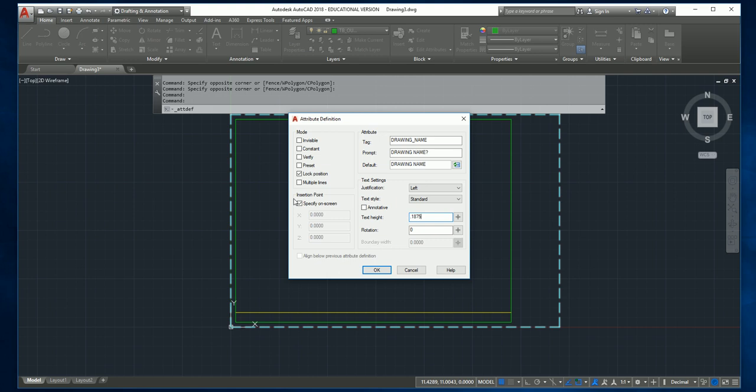How'd you get the measurement from your tick site? Oh, I'm looking at the other drawing that's on the other screen. Oh, okay. Yeah, I was just seeing what I drew there. So then do we have to put the same? Yeah, 0.1875 for the text height, or it's 3/16. You could type in 3/16 and it'll adjust. And then if we go ahead and hit OK.